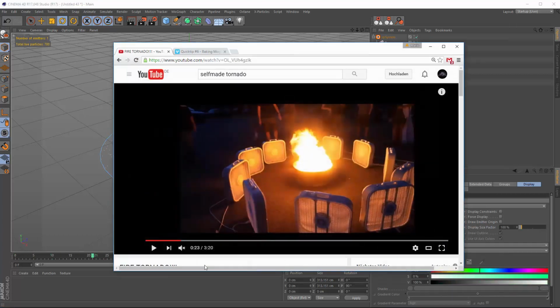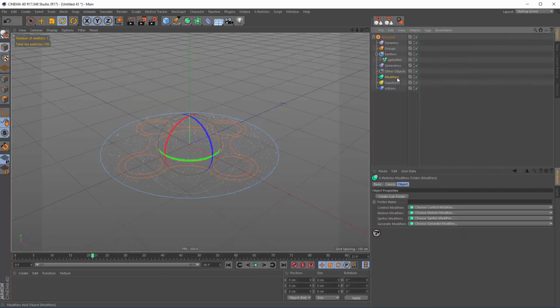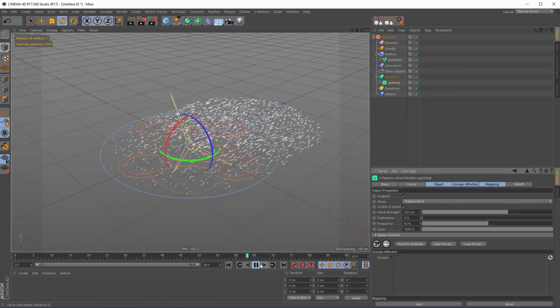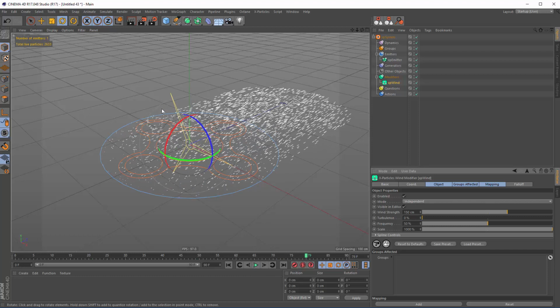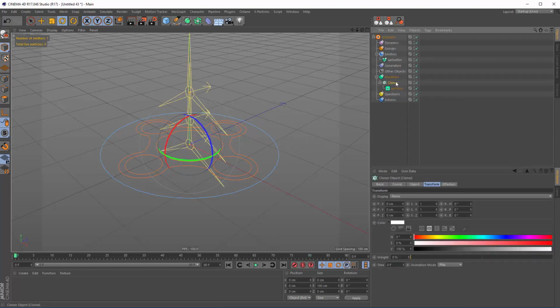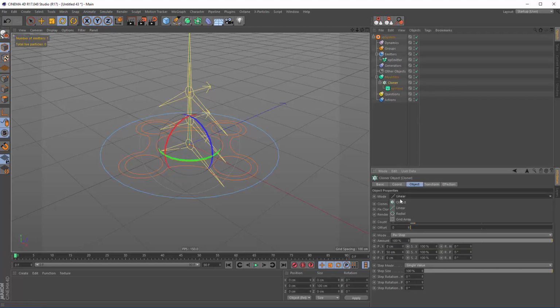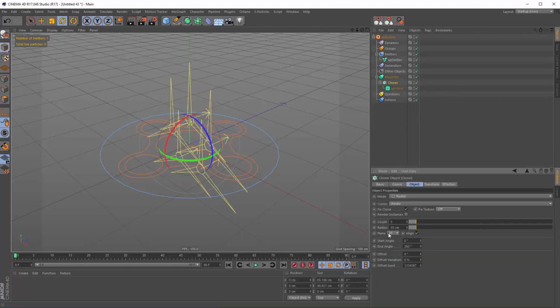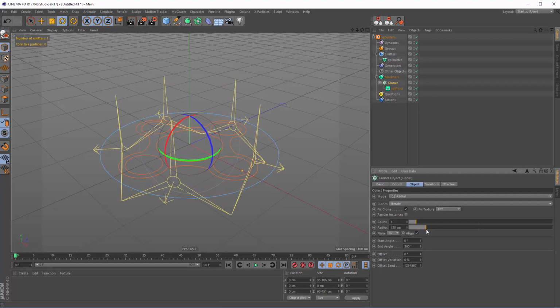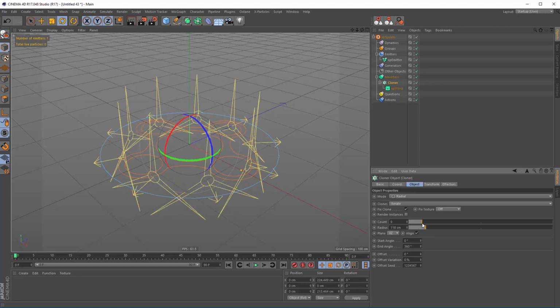Alright, so now we want to create this very nice fan rig over here. So therefore we use the motion modifier wind, and it's accelerating our particles. And to create this radial formation we can make use of the very nice MoGraph cloner and put the wind in there. And when we change this to radial and the plane axis to XZ, we can now increase the radius, and let's make it 9 fans.